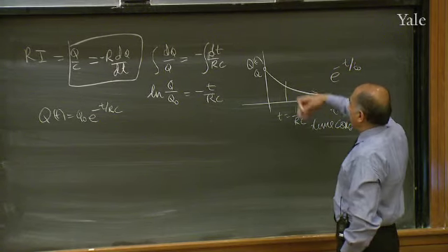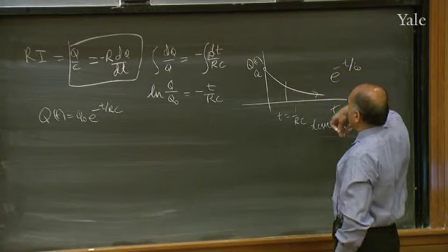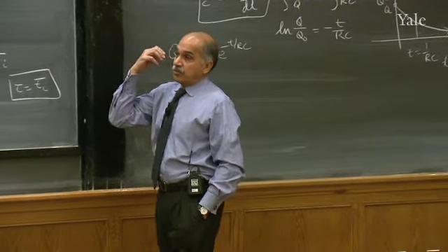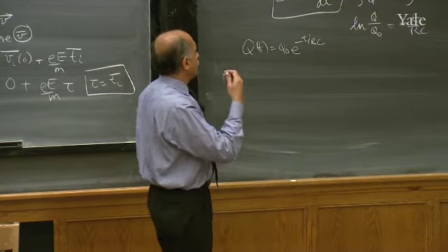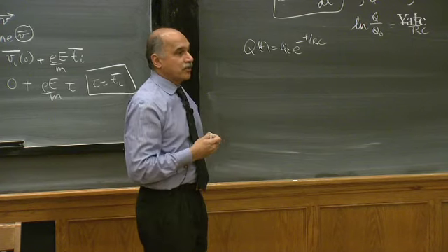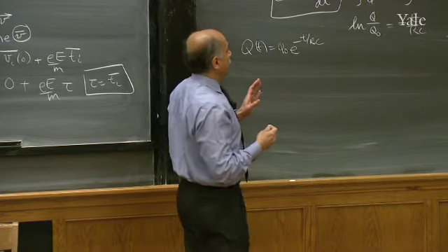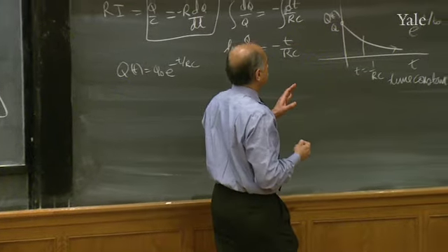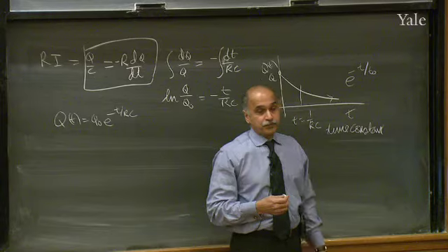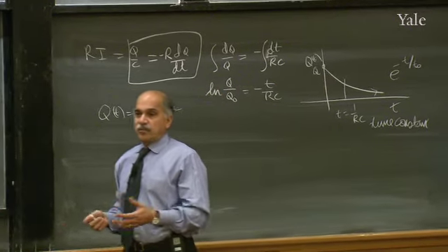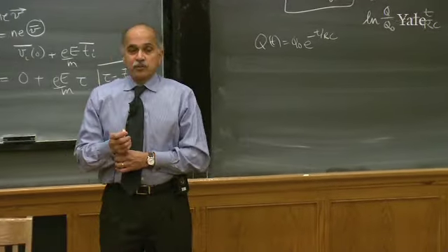So whenever you say something is falling exponentially, it doesn't mean that it may take forever, it may happen very quickly. It depends on what's up in the exponent. All exponential functions will look like e to the minus time over some other number with dimension of time. That's the unit in which you measure time. If little t is many times big T naught, then it's e to the minus big number, which is negligible. So you've got to wait many time constants before a capacitor will discharge.